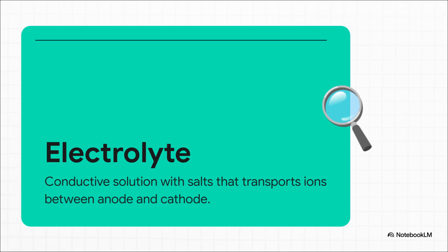It's full of conductive salts, dissolved atmospheric gases, or acids. Just think of sea spray or acid rain. This contaminated moisture provides the perfect carrier. It essentially acts as a superhighway for charged ions to transport positive current straight between the anode and the cathode.